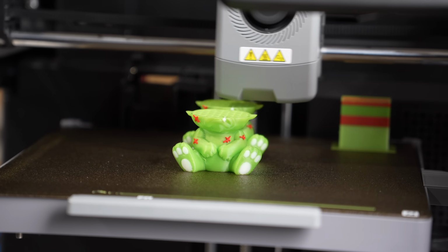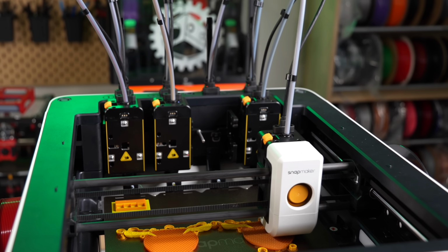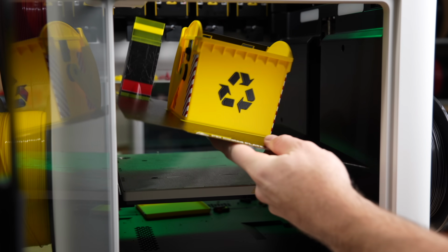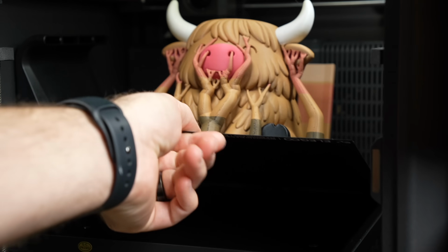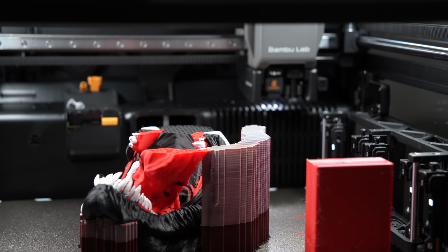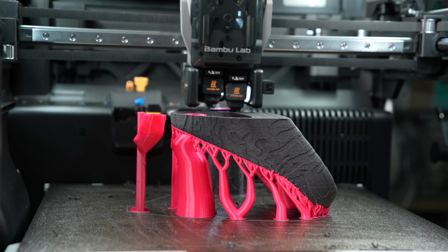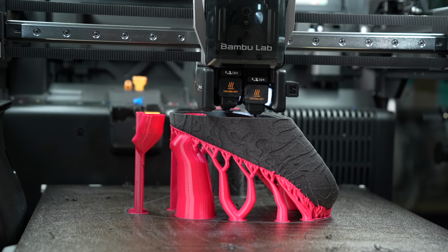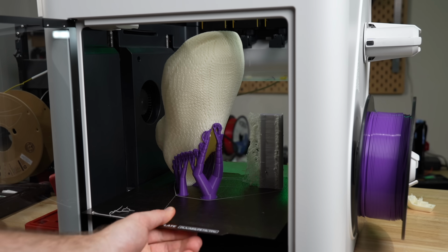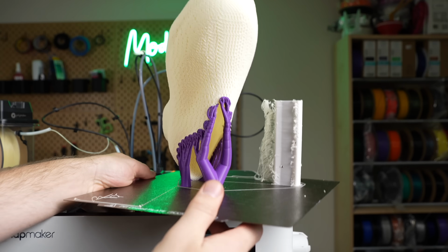Whether you're using a single toolhead filament swapper or a tool changer, when printing with multiple colors or materials, a prime tower is needed to ensure consistent extrusion. For multicolor prints, adhesion and overall stability is normally not an issue. However, when printing with dissimilar materials, such as a PETG and PLA or TPU and PLA, to have easily removable supports, the overall stability of the prime tower is significantly reduced, especially for tall prints.